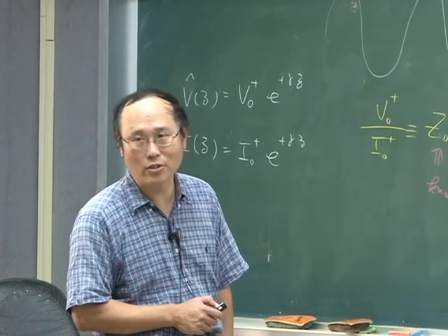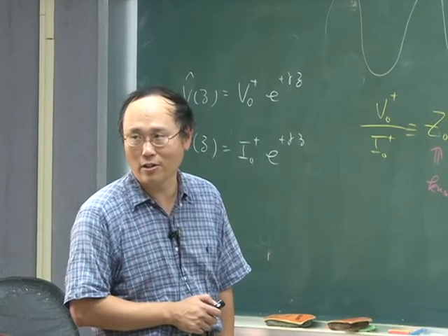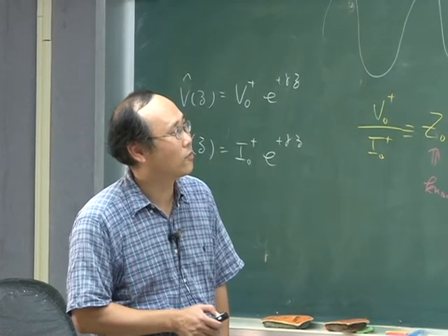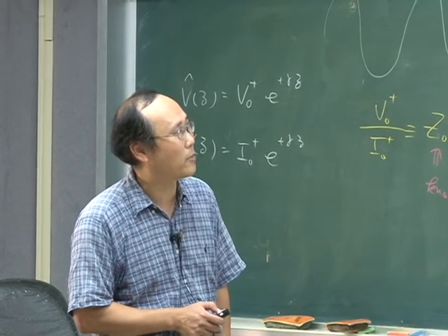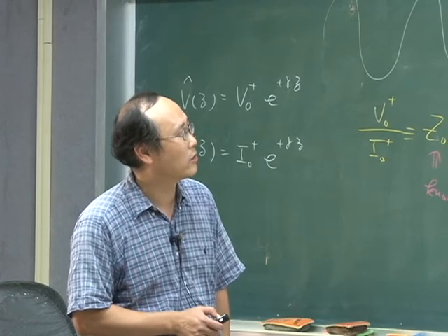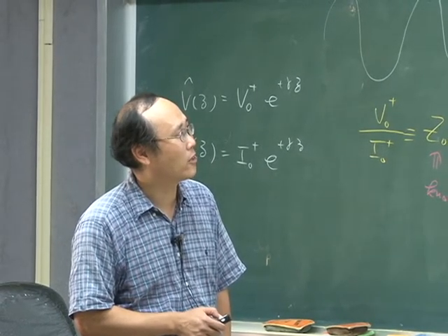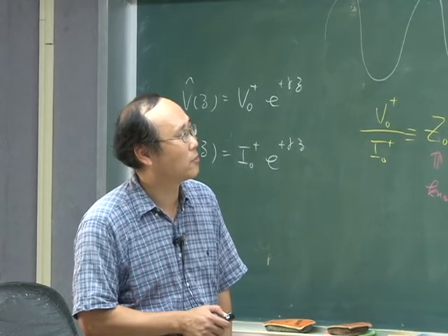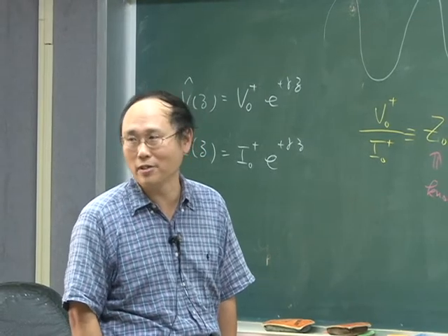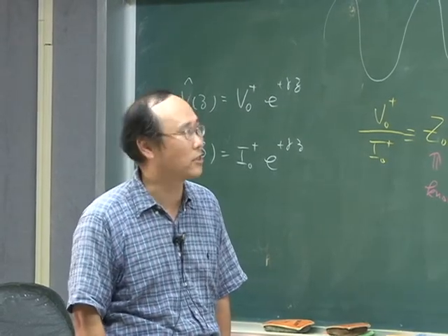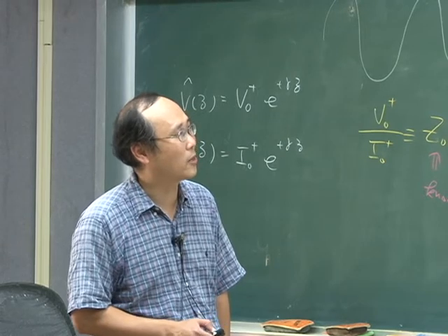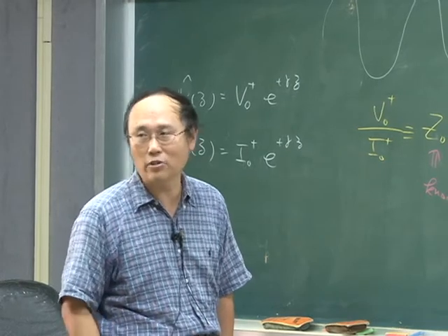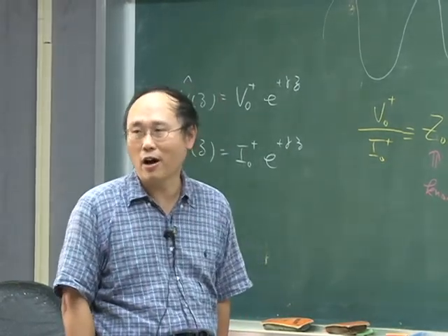This means that your resistance and conductance are 0. Then, according to this equation, if R and G are 0, then you only have a propagation term. Your attenuation is 0, so beta is very easy to calculate. Just take out R and G, then your beta is equal to omega multiplied by the square root of LC. So this is the simplest case. And the phase velocity can be calculated, which is 1 over the square root of LC, and ideally L and C are independent of frequency.